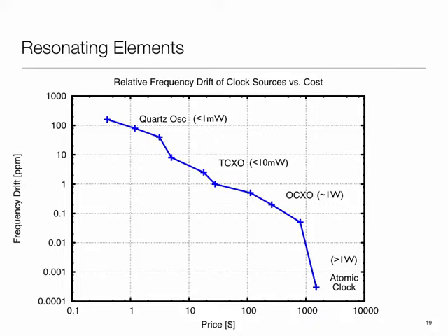It turns out that since quartz oscillators are basically oscillating crystals, their mechanical properties can be modeled as a function of temperature. It turns out they follow a cubic curve. So you could either learn the parameters of that cubic curve, or alternatively, you can subject the oscillator to different temperatures prior to shipping and then note down the compensation. Typically, what's done is that they make a batch of oscillators. They would probably suffer from the same error because any error that crept in comes from the same crystal. They sample some of those oscillators.